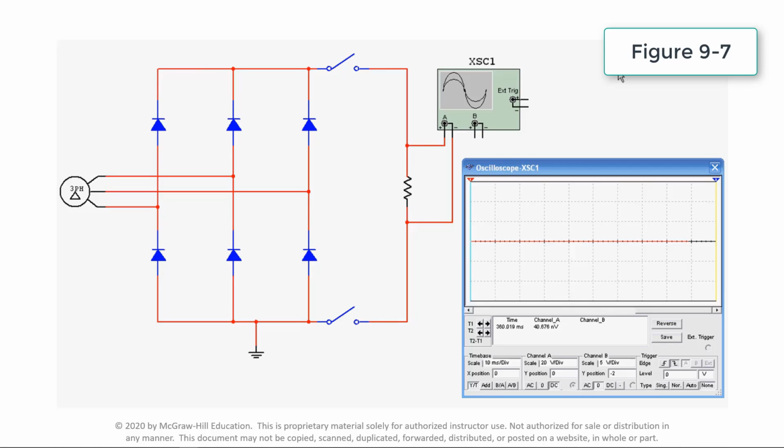This video demonstrates the operation of a three-phase full-wave bridge rectifier circuit. For heavier load demands, such as those required for industrial applications, rectifiers may be supplied from a three-phase AC voltage source. Using three-phase power, it is possible to obtain a low-ripple DC output with very little filtering.